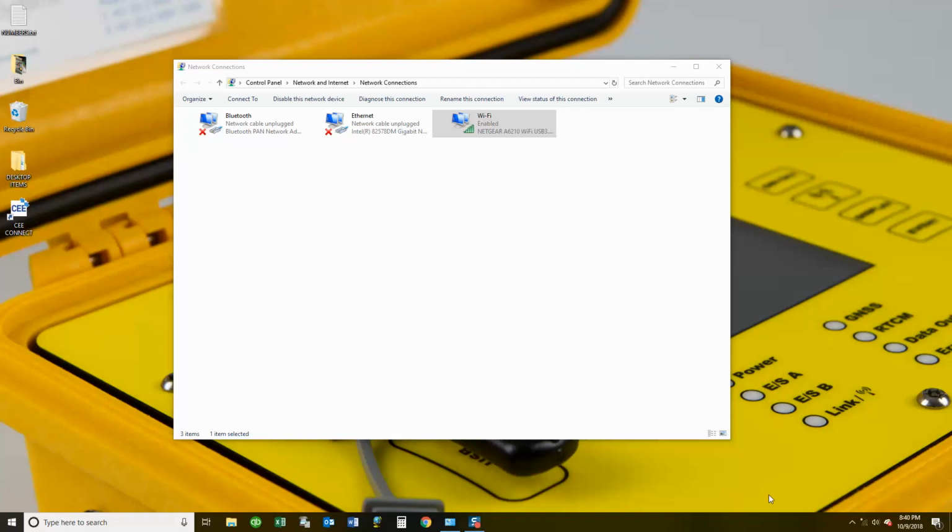Now I'm going to explain the connection method to connect to either the CEESCOPE Lite on the USB or the CEESCOPE USB echosounder with a Wi-Fi direct connection. Usually those systems will be using the C-Link shore radio, but instead of the C-Link, a computer with a Wi-Fi card that has dual band or 5 gigahertz Wi-Fi can connect directly to the echosounders. Alternatively, a USB radio dongle can be plugged into the computer or the tablet to connect directly to the echosounder. To do that, you have to change the settings of the Wi-Fi adapter. We already looked at the Ethernet adapter settings, the LAN port, but in this case, the echosounder is going to be connected directly to the computer with its Wi-Fi system.